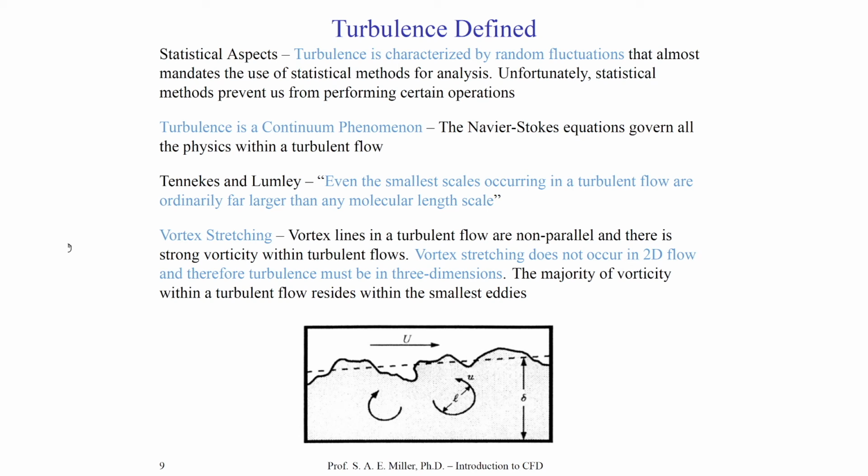Vortex stretching does not occur in two-dimensional flows, and therefore turbulence must be in 3 dimensions or higher. And the majority of vorticity within turbulent flow resides within the smallest eddies.